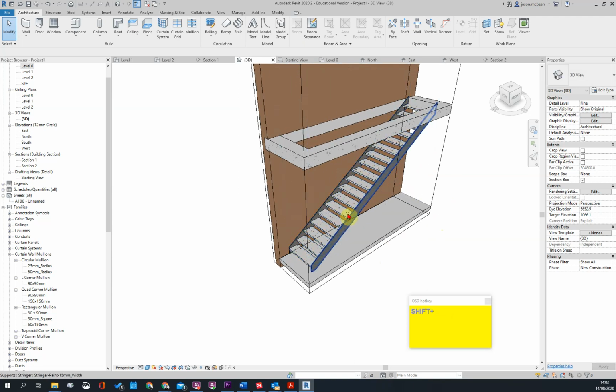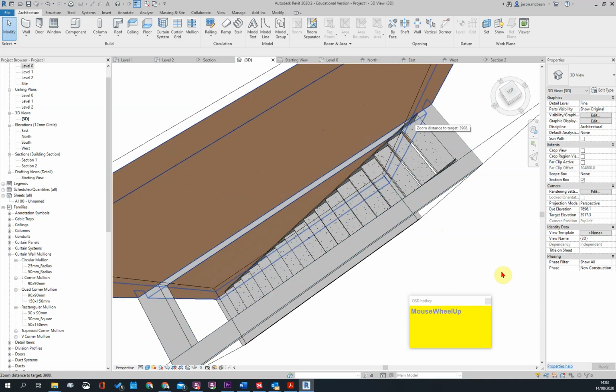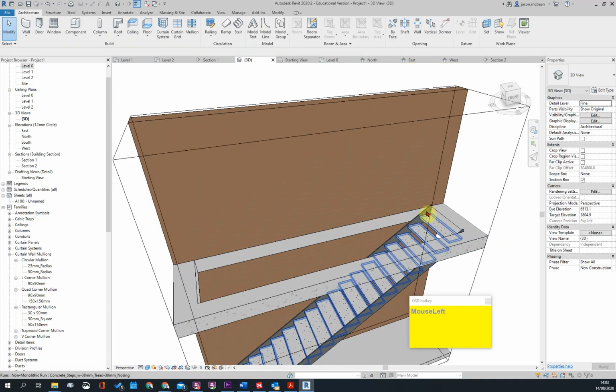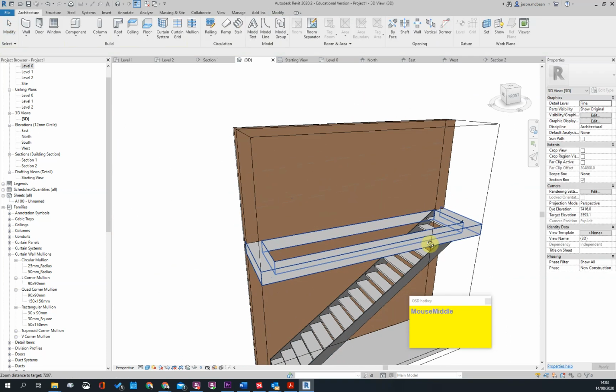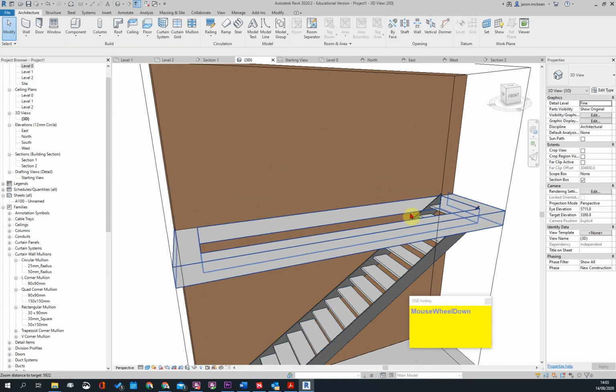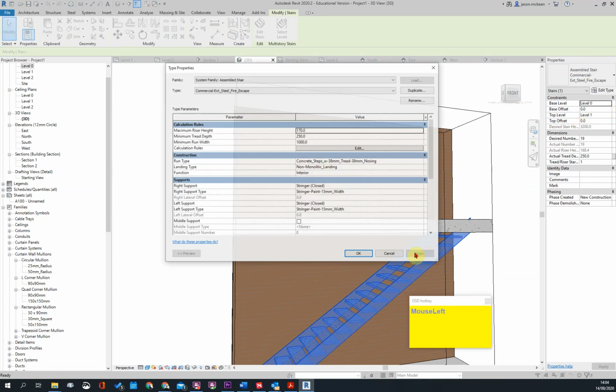Just bear in mind, if you want to really customize staircases, sometimes you have to model them in place. Okay, and how these things terminate. Unfortunately, sometimes you'll have to remove that stringer. So you can remove stringers from a stair, for example. So you could just have the floating sections without sections and then model in how the stringers work on the side. Okay, so that we'll cover a bit later as well.